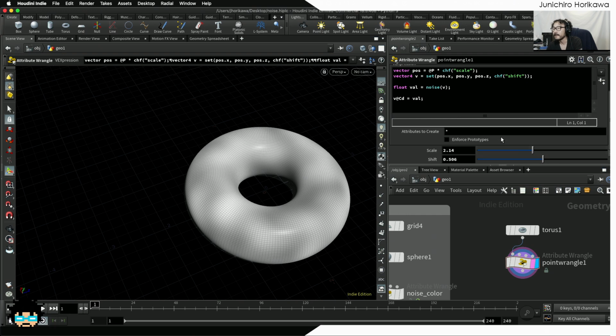Now what I want to do here is, out of these values, create a ripple-like pattern by extruding or moving the point coordinates up and down like a ripple wave. Now to do that, one idea is to use this value as an angle for the trigonometry. Okay, meaning I can use a sine function, and inside this sine as an angle I can use this noise value and use this result as a value to move this point in the normal direction. Okay, so let's try that out.